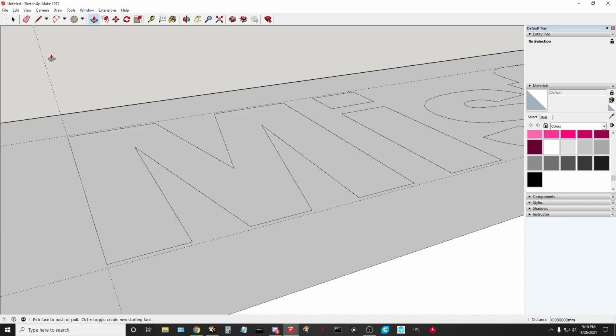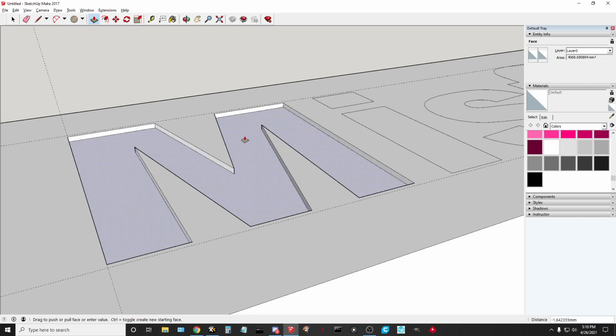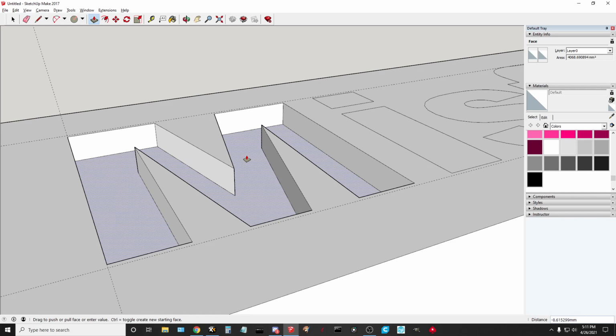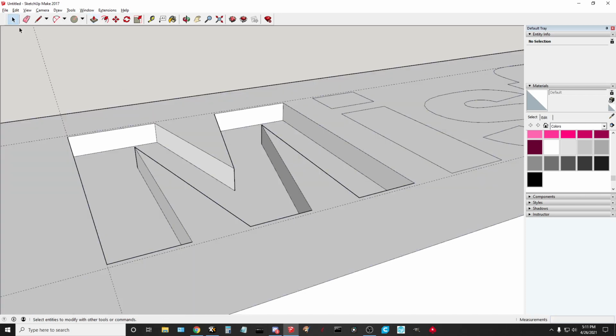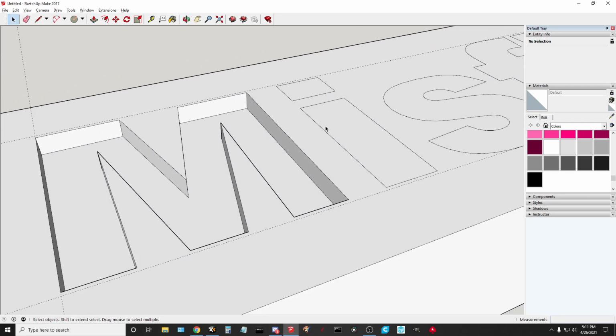Or we can click it and then move the mouse without holding the button and see how it's a free rein. And now I can actually let go of the mouse because I just left clicked and not holding the left button. And I can type in the dimension I want, and it will put it right there. And sometimes when you start doing it, it might remember that you went 7, so let's try it again. No, it's not going to let it, so 7.0.